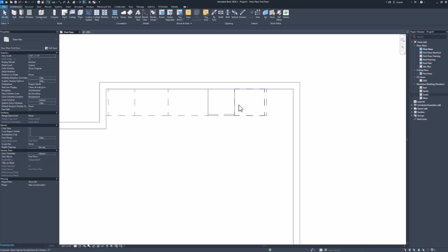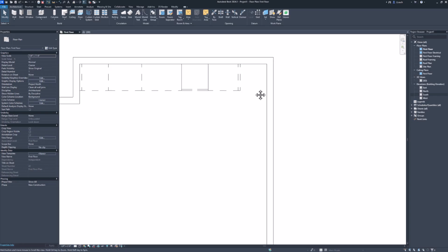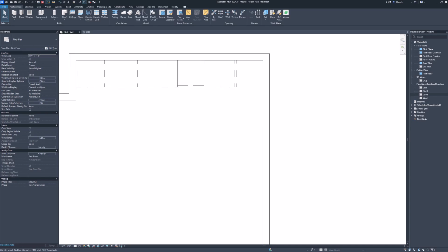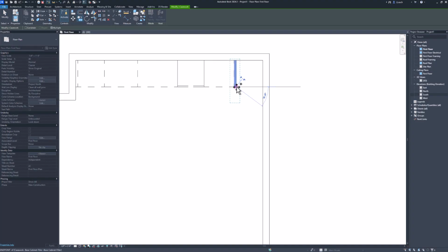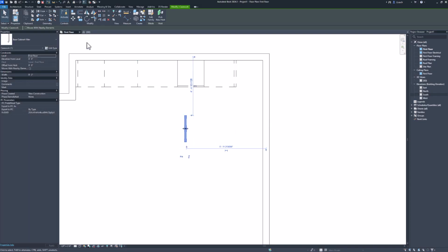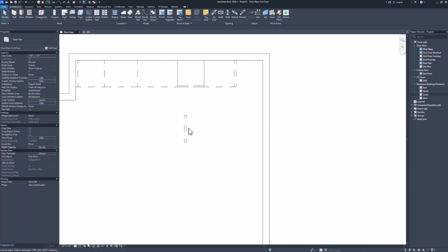And now we want to turn this corner and put some cabinetry on this wall. So these two cabinets, when you open them up, they're not smacking into each other, the doors. I'm gonna put another 2-inch filler. I'm gonna select this. I wanna copy this one. I'm gonna copy, just left click somewhere. I'm gonna copy it over here. Rotate, cancel, hit modify to get out of there. So I brought it way over here because we need to rotate this.